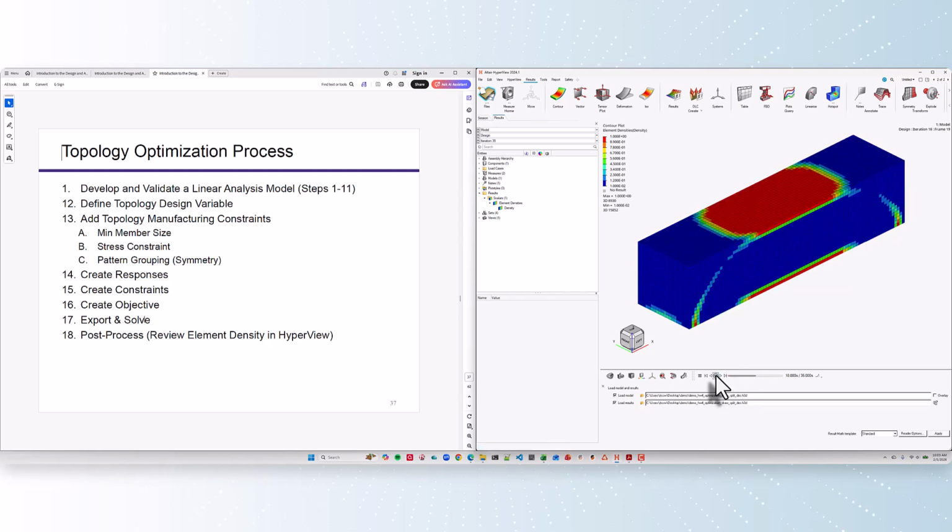And you can also hit the play button. It will just play you what every iteration is doing as it's going through its optimization engine path. But of course, the one that you want to focus your time on is the last one. It's the converged one. It's the solution, the final optimization solution. And you can see here that density is somewhere between 0 and 1. And this is great. But what's hard about this view is that what I really want to do is all of the elements that have a density less than, let's say, 0.7, those are elements that are not there. And so I want to tell the computer, I want to visualize this better. I want to remove those elements because it says these elements don't exist.